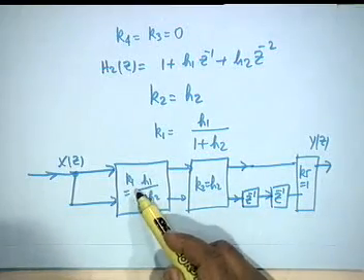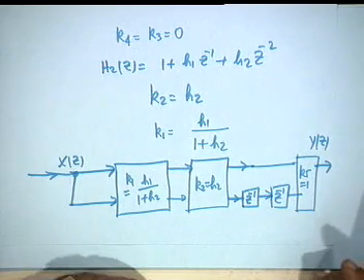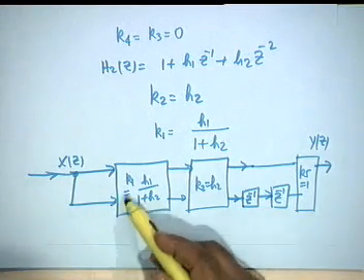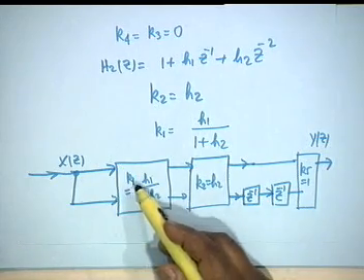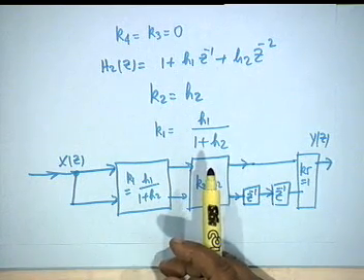Okay, so it simplifies. Now you see the number of multipliers. Number of multipliers is twice 2 here, 2 and 2, 6, which should have been 3 in canonic. Okay, should have been 3. But can you have a single multiplier realization of FIR lattice? We did it for IIR. For FIR, that's an open problem till now. Okay, we might solve it later.